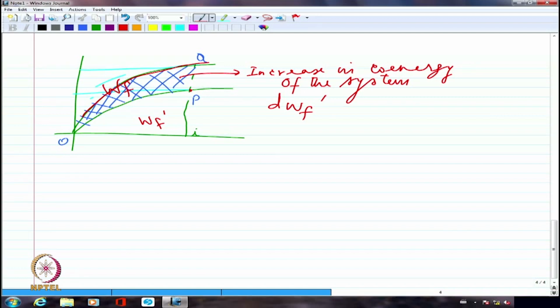In the previous case, we considered there was no movement. We considered only one particular magnetization characteristic. Whereas in this case, we have considered two magnetization characteristics, one at air gap length x1 and the other at air gap length x2. And we considered x2 is smaller. That's the reason why we considered the curve above the previous curve, assuming that the reluctance is smaller, because of which the flux should be larger.